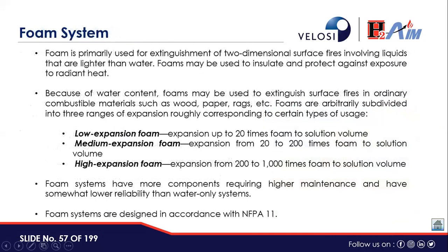Foam system. Foam system normally, as you see, is for storage tanks, especially floating roof tanks, so a foam system is installed focusing on ring main fires. So there are pourers of the foam, and foam has two things: one is the substrate or chemical, and then the water. Both the foam substrate and water are mixed at the time of activation, and then foam is thrown on the destination.